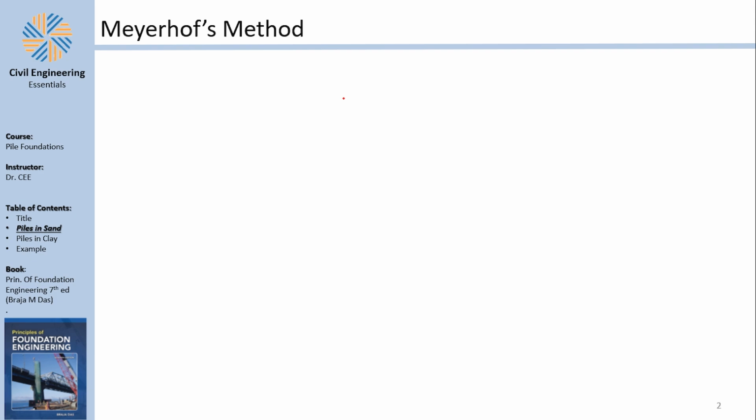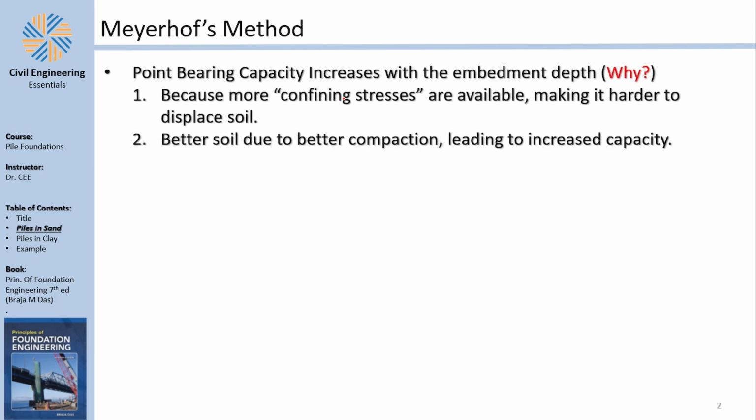Alright, so let's take a look at Meyerhof's method. In Meyerhof's method, basically the tip bearing capacity will increase based on the embedment length. The embedment length, if you remember, is the length of pile inside the soil that you are considering. Now, why is that the case?